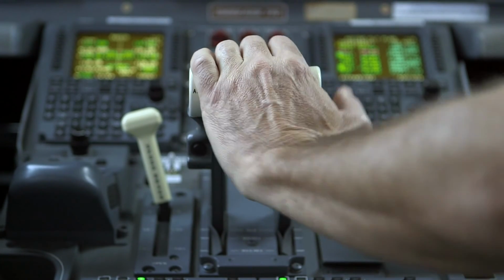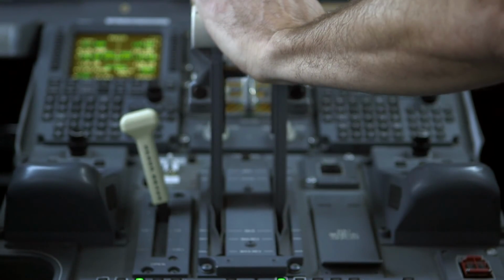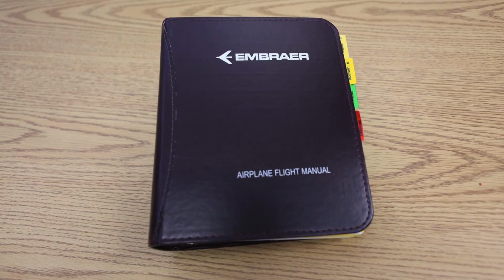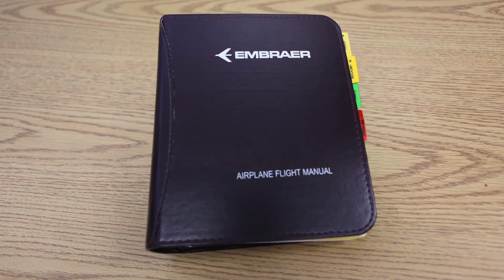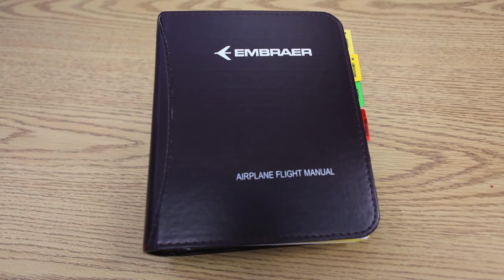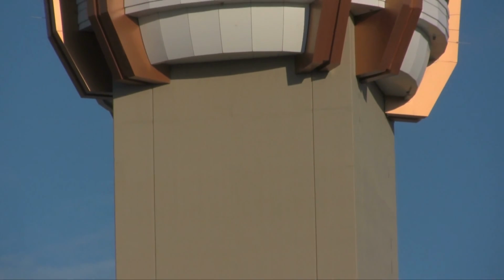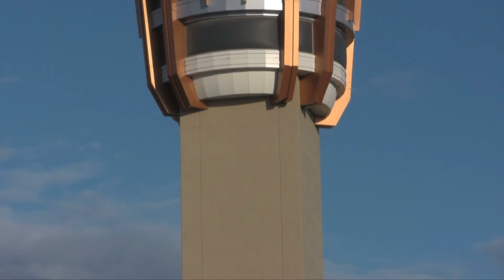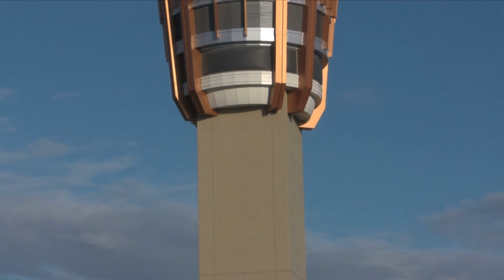Performing a missed approach and loading a different approach procedure should also be considered. Refer to your Embraer aircraft flight manual for guidance on SBAS fail-down procedures and requirements. Pilots must notify air traffic control of any loss of GPS or SBAS capability and state their proposed course of action.